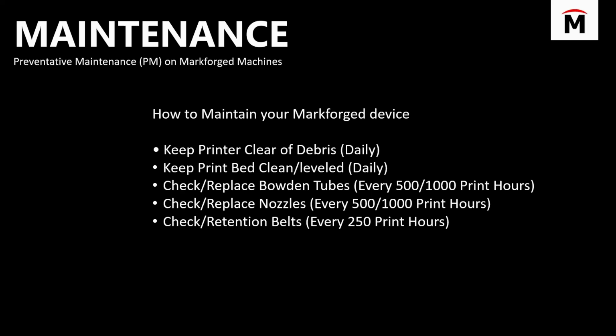As you can see, this is a pretty short list. Let's start off with daily maintenance. What is required daily or weekly to keep these machines in top shape? How about 10 to 15 minutes or less? We're talking about keeping the printer clear of debris, keeping the print bed leveled and clean, and checking your material levels just so we know we're not about to run out of material anytime soon.